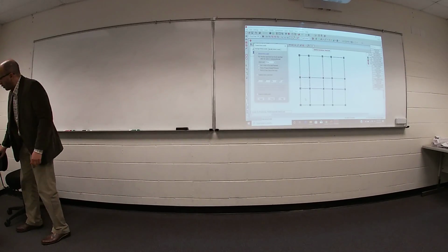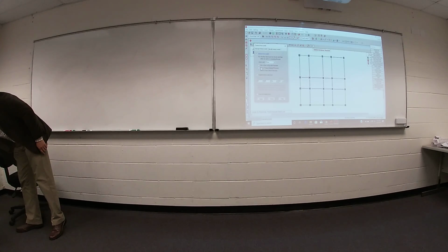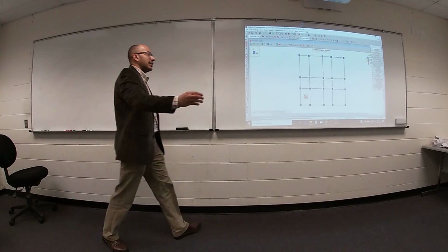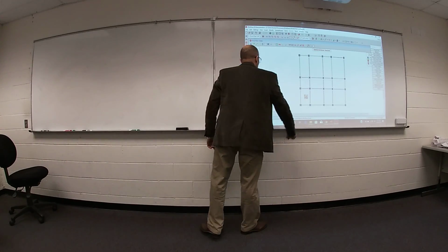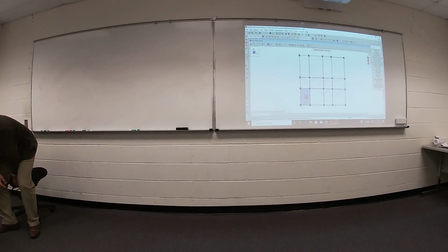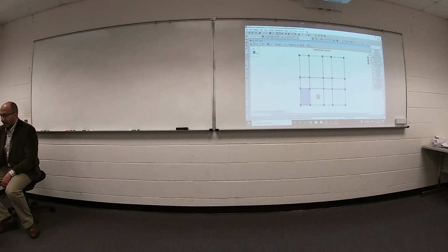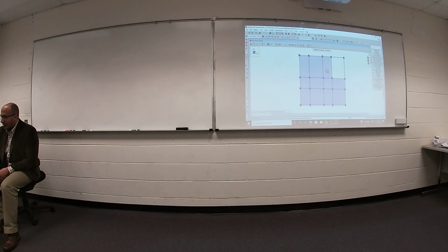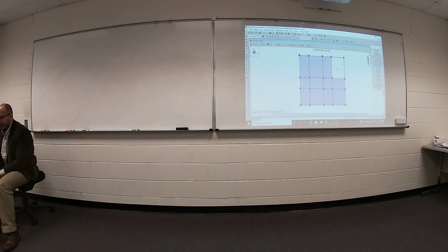So I will check the first option. Just click, apply. Just click at any point inside your panel. You will define area load for this area, like this. Just one click. We have stairs here. This area is empty area.